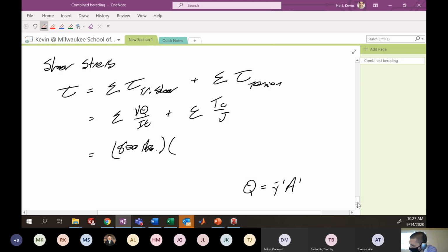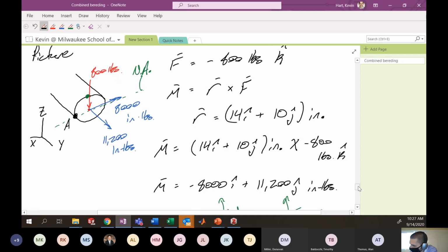When we're looking at this transverse shear component, we're looking specifically at point A. So when I identify this point, I want to draw a line across my member perpendicular to the applied load. At point A, I can draw this line across my piece at the point of interest, and the length of this line is the little t in the equation VQ over It.